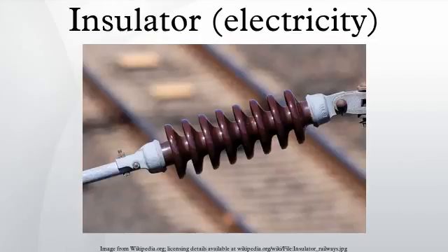Types of insulators. These are the common classes of insulator. Pin-type insulator. As the name suggests, the pin-type insulator is mounted on a pin on the cross-arm on the pole. There is a groove on the upper end of the insulator. The conductor passes through this groove and is tied to the insulator with an annealed wire of the same material as the conductor.